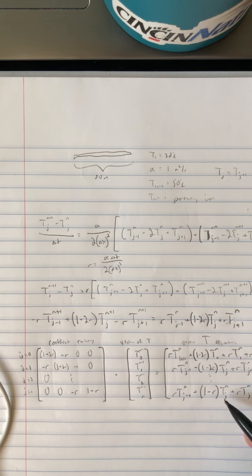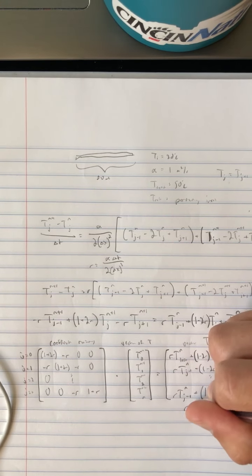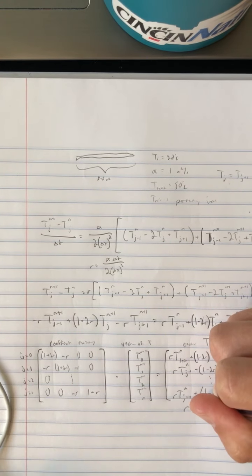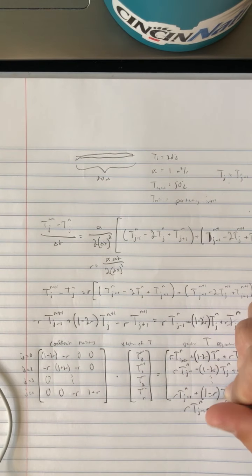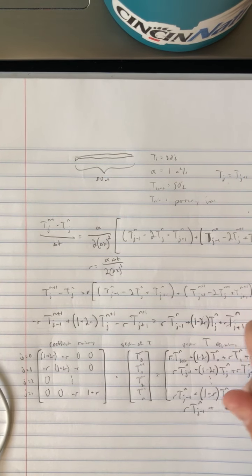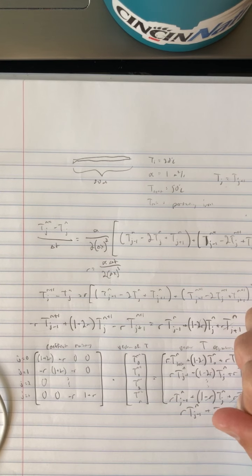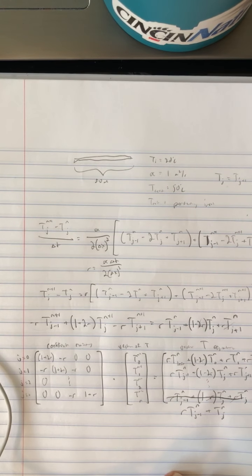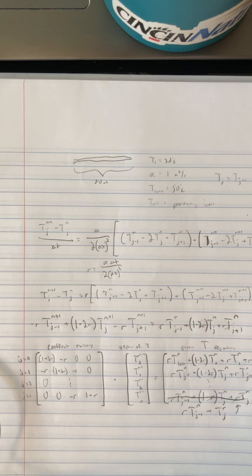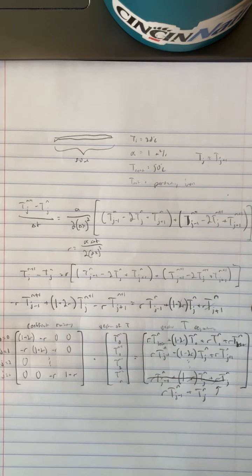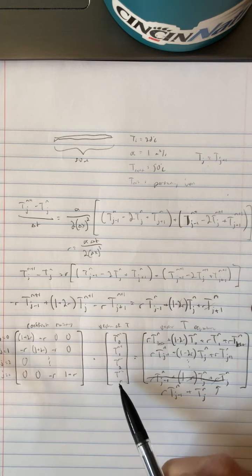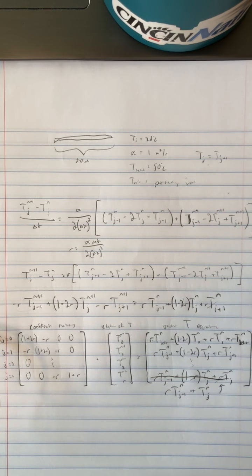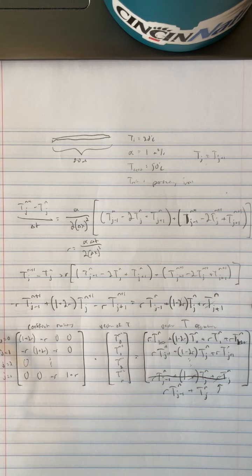And then now that we have this, it'll be able to cancel out the second r, so it'll end up being r times the temperature to the left at the current time, plus the temperature at the current position at the current time. So now that will fill in our final line. Now that we have the matrix and these two vectors, we will be able to plug this into Python and solve for the unknown temperatures.